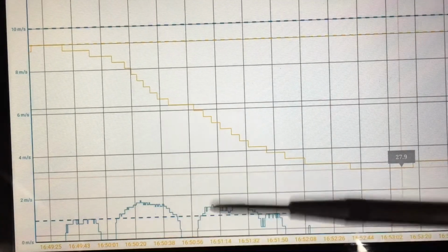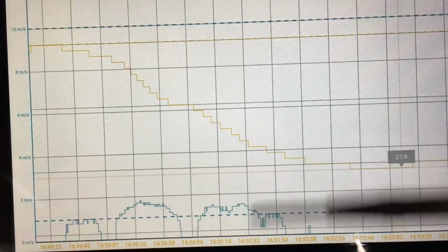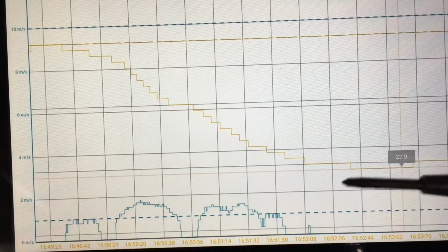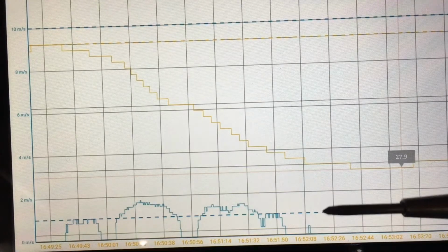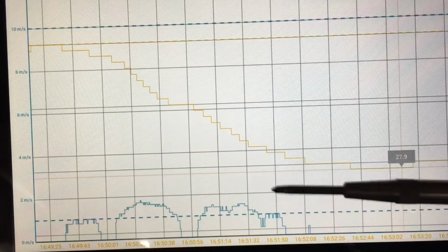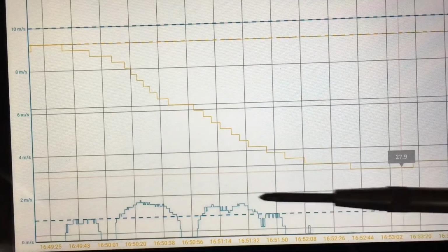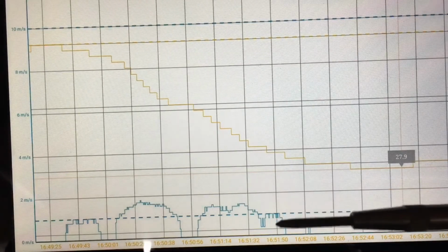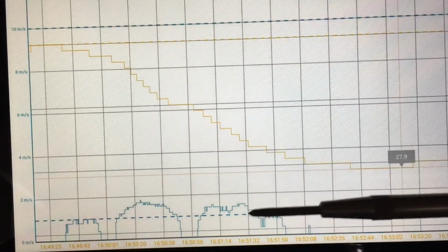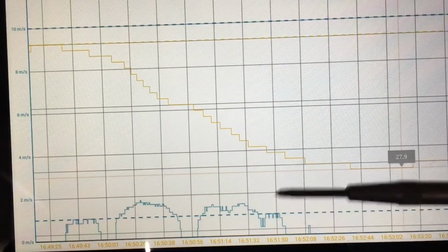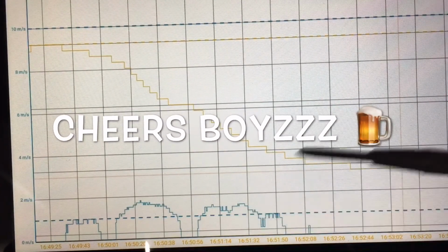So this is kind of interesting, I think. Not only does your climate control want to know the vehicle speed because there's more airflow through the condenser coil up front, and more flow from a heating standpoint through the radiator, but it also wants to know the vehicle speed because there'll actually be a natural increase in flow through the ductwork. So I suspect the algorithm may anticipate that increase in flow and actually slow the fan speed in order to maintain or attain a temperature. It's all considered pretty interesting.